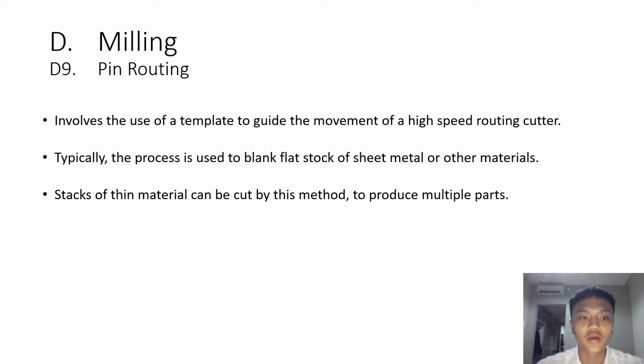Pin routing. Pin routing involves the use of a template to guide the movement of a high-speed routing cutter. Typically, the process is used to blank flat stock of sheet metal and other materials. Stacks of thin material can be cut by this method to produce multiple parts.